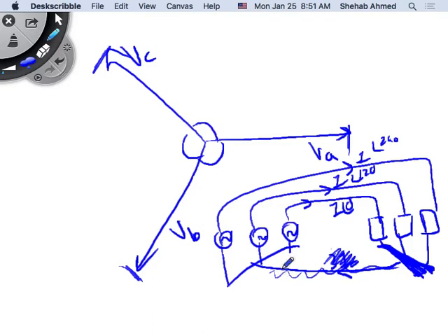But if the voltages are not perfectly balanced, this does not hold. We will have some neutral current, and these 3 will not sum up to 0. So in that case, we will use a mathematical tool in chapter 7 called symmetrical components. It will allow us to take these 3 waveforms and chop them up into a positive sequence that is balanced, a negative sequence that is balanced, and also something called the zero sequence. Why do we want to do that?